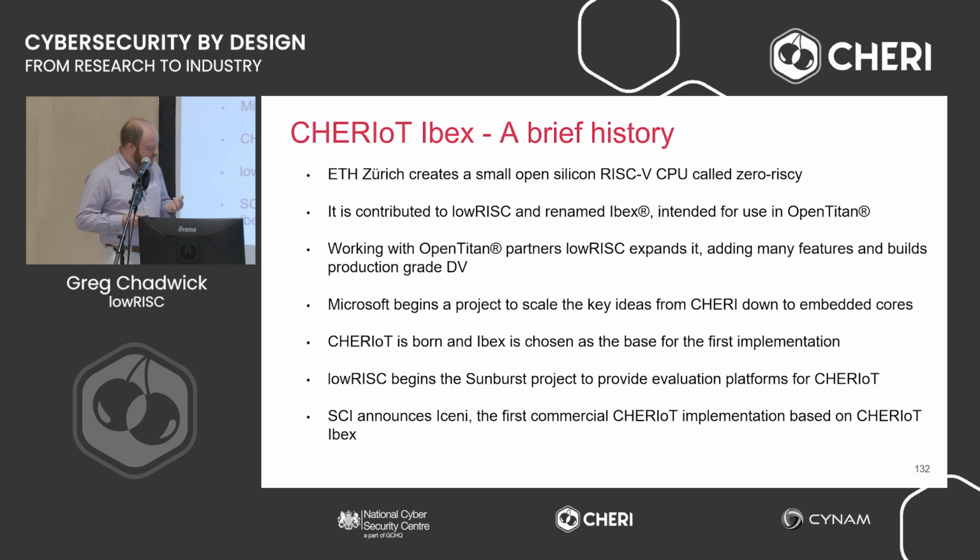So now it's interesting to maybe talk about CHERIoT Ibex. I'm not going to go into all the details about CHERIoT, but fundamentally, CHERIoT is a cut-down form of CHERI, or a form of CHERI that's been targeted at lower-end use cases. It's designed for embedded hardware, things like operational technology, IoT, and so on. And I think it's a lot of these cases that the earlier Digital Security by Design cohorts were finding people were interested in, and they were spending all their time trying to work out how to make the Morello board interface with these little peripherals they have. They maybe wanted something lower end to start with.